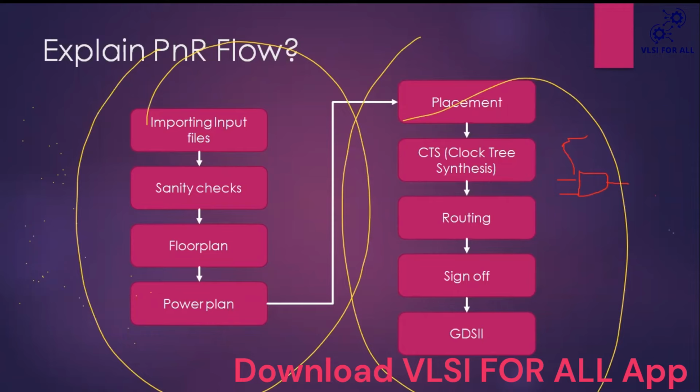Here we should compare the netlist and the .lib file. All the standard cells present in the netlist should match the .lib file. Then only we move forward. For timing, if there are any missing constraints in the SDC, we have to check that also. If everything is clean, then we start floor plan.